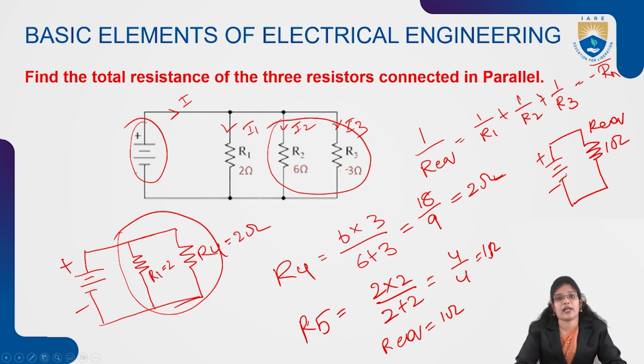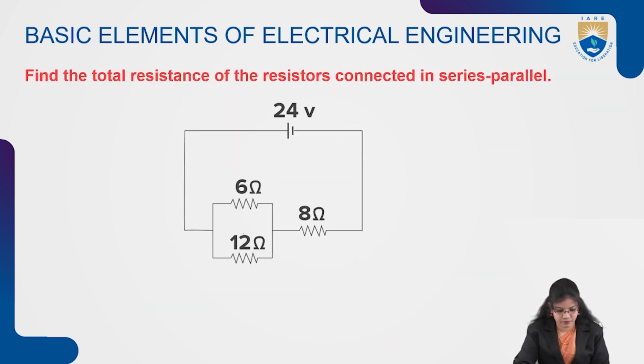In this way, we need to calculate the resistance when they are connected in parallel. We have to remember that when the current is dividing in the circuit, then the circuit is said to be in parallel. If the current is the same across the circuit, then it is said to be in series. In the series parallel combination, the current will also divide and the voltage will also divide depending upon the circuit.